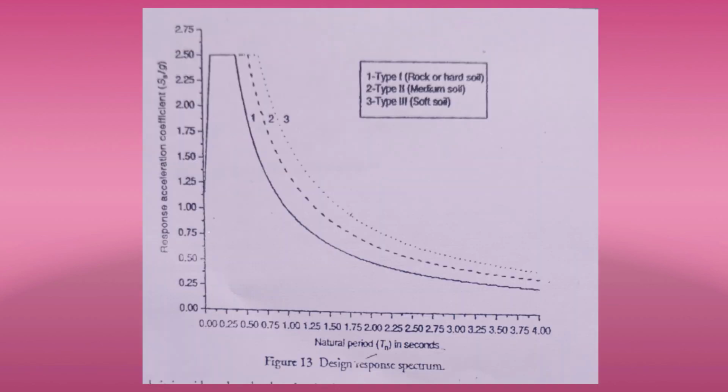That is known as the design response spectrum. It is generally represented in normalized form, as in the case of the normalized elastic response spectrum. It is also shown in IS 1893 2002 and IS 1893 2016 nowadays, and it uses the normalized PGA, that is peak ground acceleration,